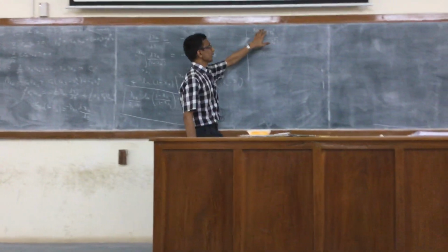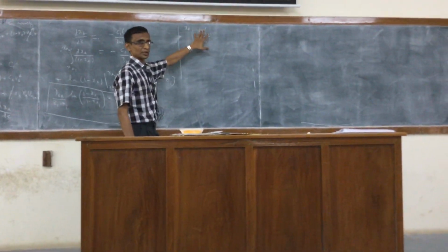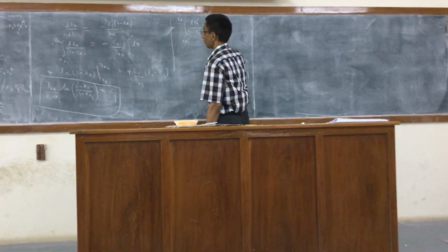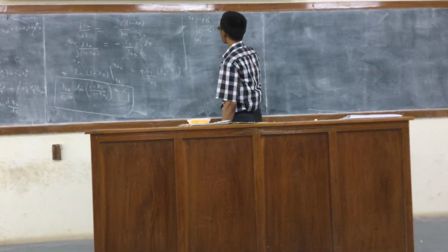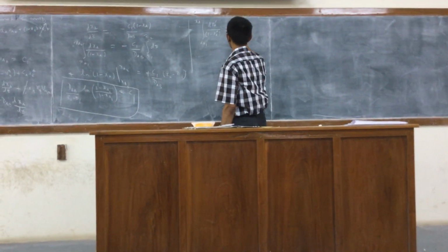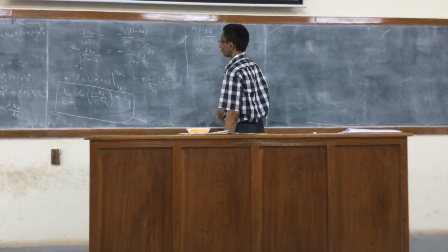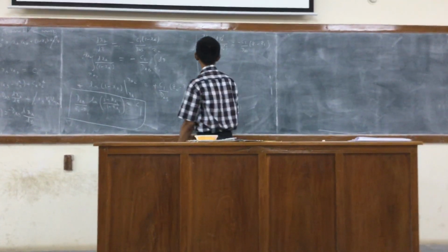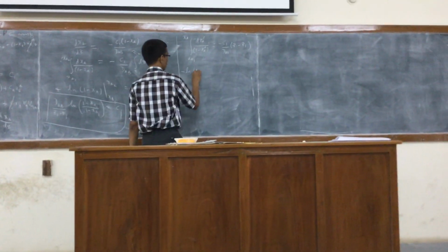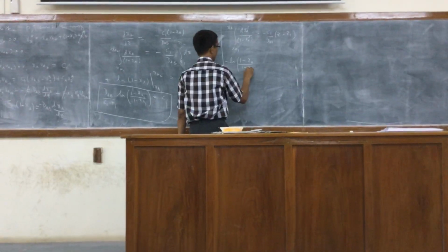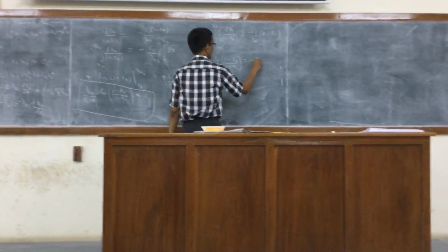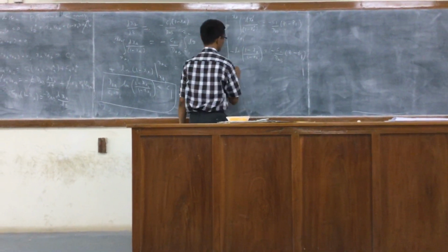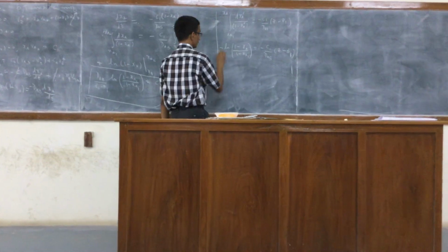So I don't want to keep the same variable, so I want to distinguish it. So I am using a dummy variable of integration. This would then be minus C1 by DAB, and this is simply going to be Z minus Z1. So then I again have minus log of 1 minus XA by 1 minus XA1 is equal to minus C1 by DAB times Z minus Z1. So I can get the profile as